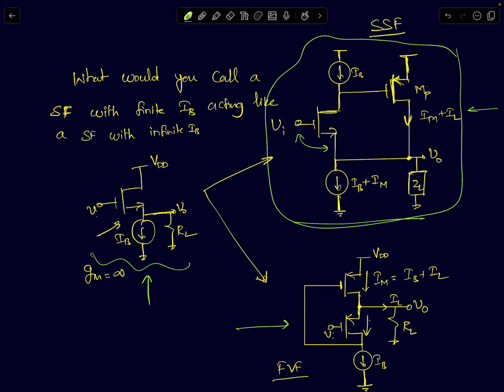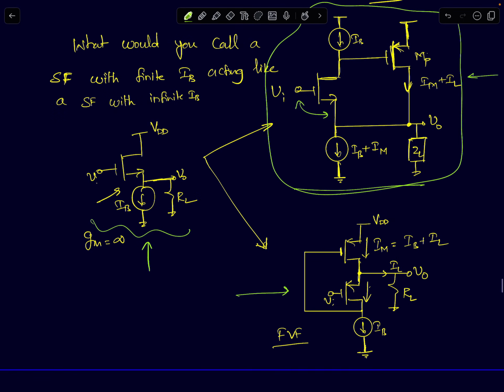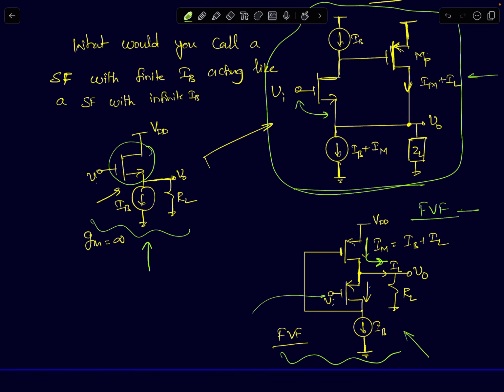The difference is that functionally, this structure is very similar to an NMOS source follower because it can also supply source current to a load resistor. So functionally it's similar to that, but you have a device flipped. Here it's an NMOS device, flipped to a PMOS here.